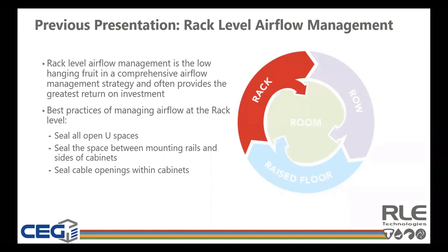If you're 52U, you've got about 96 inches by 4 inches wide of an open gap that they use for a lot of high density cabling, typically. Those need to be blanked off as well so that hot exhaust air from the rear of your racks doesn't wrap back around through those big gaps. Brush strips are most commonly used there because you can reach your hand through it if you need to, penetrate that with a cable and still block the opening.